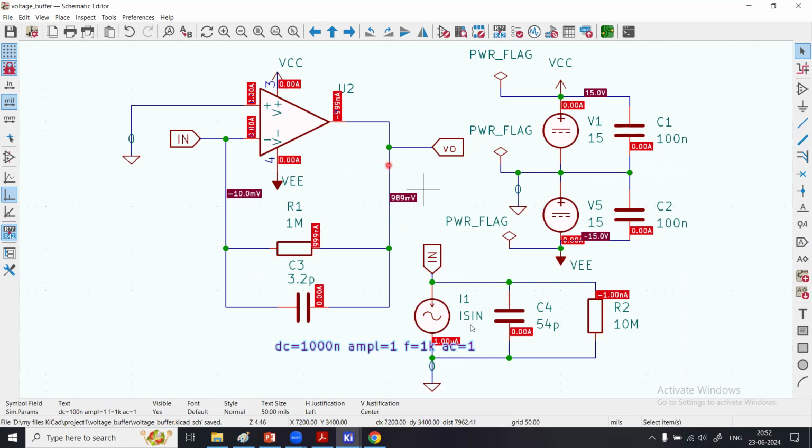You want to understand up to what frequency of this signal current the amplifier will perform the current to volt amplification in a linear way, right? To verify that, we have to simulate its frequency response, where we can do the small signal AC analysis. So let us do that.